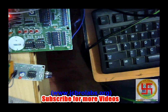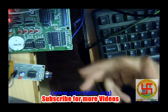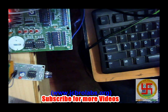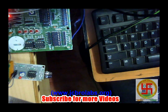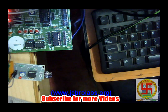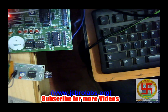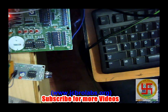So in a sense, when this range is small, we can convert a normal obstacle detector IR sensor into a color detector IR sensor. So it can't detect black surface, but it can detect white surface. So we can use this particular property of this IR sensor while making a white line or black line following robot. Now in normal mode we can use this particular sensor in an obstacle avoidance robot.